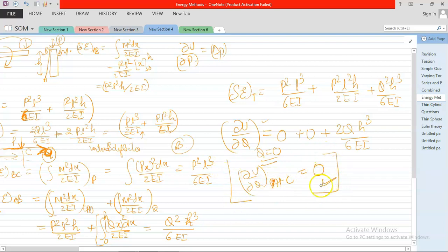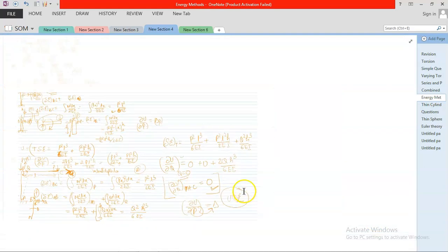But in some other cases there may be a horizontal deformation. So what I want to say is, in this theorem, if you are obtaining the deflection in that direction where the P is applied, you cannot apply this formula to a uniformly distributed load. So how we obtain it in a uniformly distributed load, I am going to explain that.